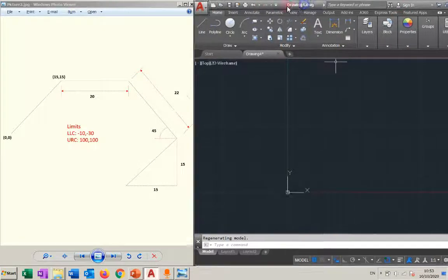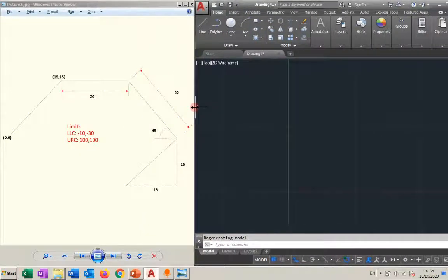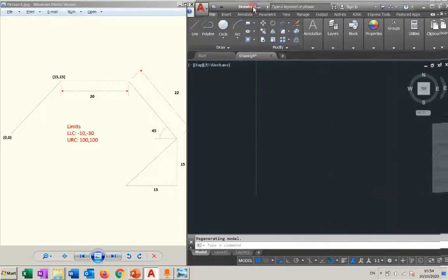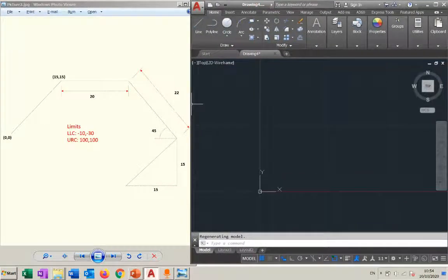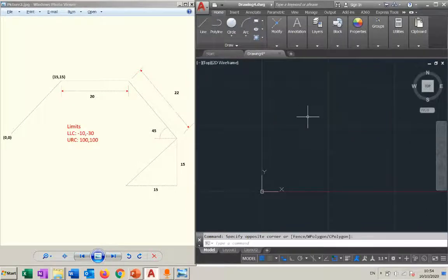I believe the AutoCAD is making it smaller. Now I'm going to Z, A, enter to make sure the limit is okay. Now we're going to start with line. We're going to start at 0 0, so 0, 0. Since it's the starting point, even if it's absolute coordinate, you don't need hashtag. Hit enter. Well, I said that some of the versions accept even hashtag.